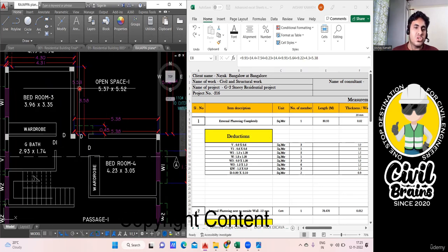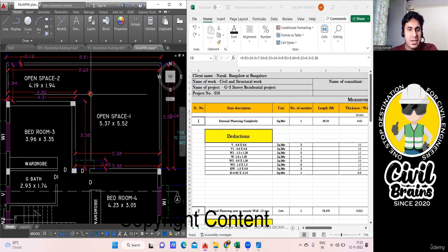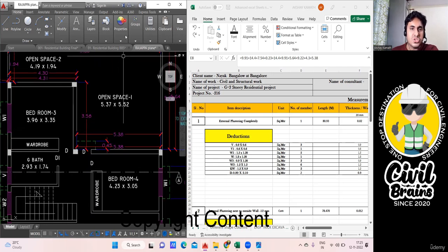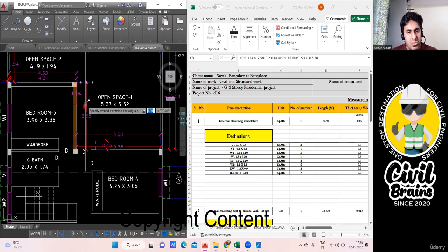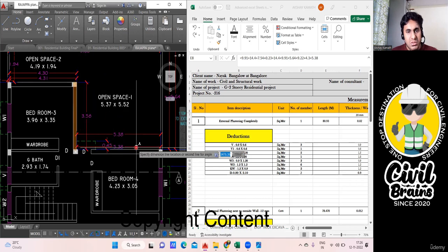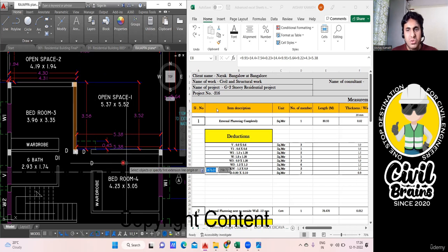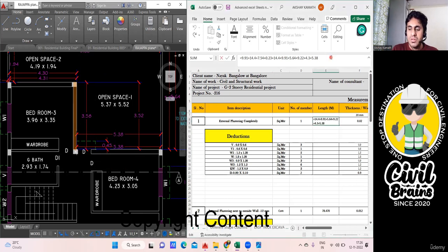And after that, this portion plastering will happen, right? So how much do you measure for this portion? If you're finding it difficult, I'll just delete this part. Delete it. And this you tell me. This portion I want. Which portion? Where the plastering will start? From here it will start, exactly from this end, and go up to here. Okay, up to here your plastering will happen. So this dimension you tell me. I'll measure from here outer to this part. So it is 3.52 for me. So I'll add plus 3.52 and enter. Done.